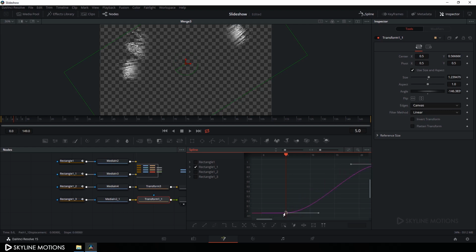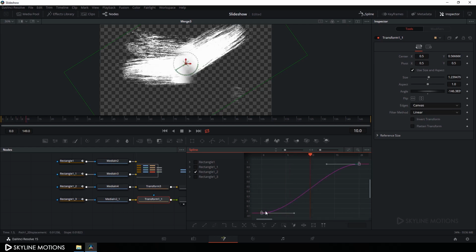Now it starts from frame number 5 to 25. Check this third one, click on the fit button, select this keyframe and move it to frame number 10. Basically, create a time gap of 5 frames. So drag it to frame number 10.